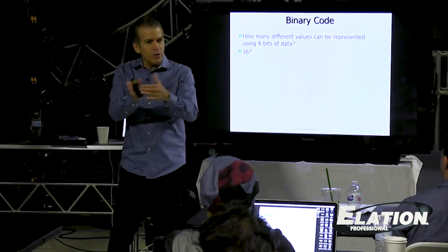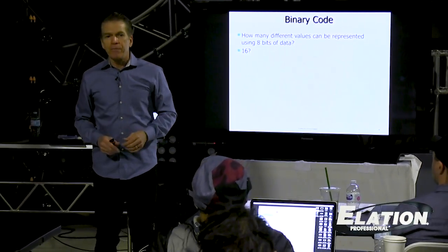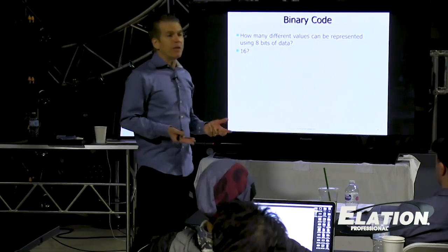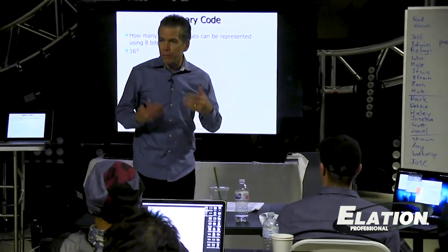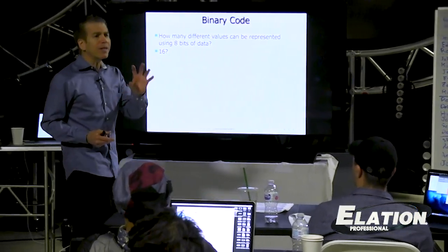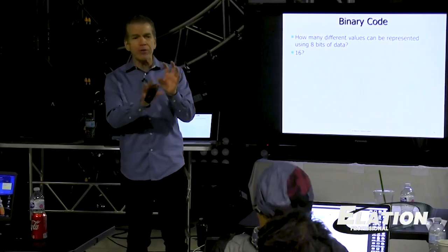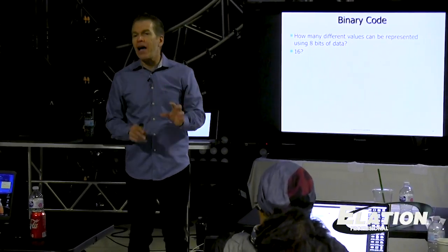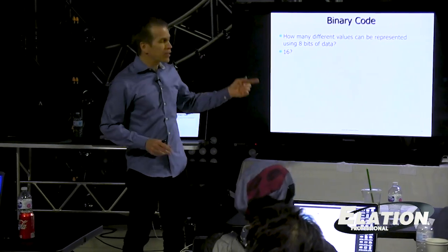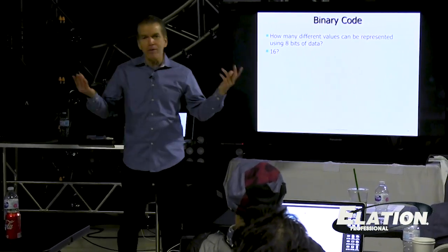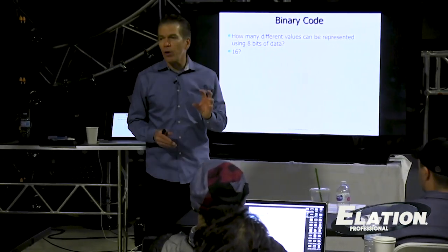You can divide it 256 different ways. In some instances, that's plenty of granularity of control. So for example, if you're trying to dial in a color wheel with 8 colors plus open, that's only 9 slots. Then 256 divided by 9, that's plenty of control.